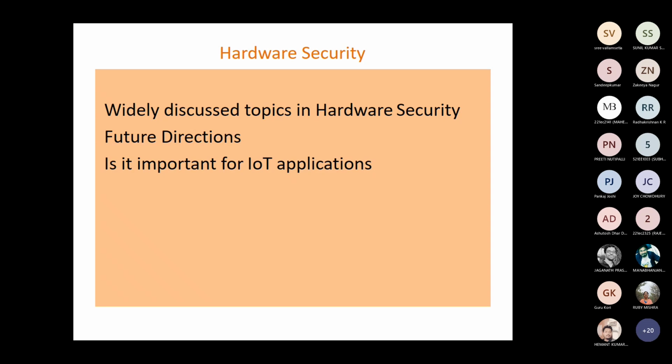Now, when I say hardware security, this will be a specifically designed integrated circuit that will have security right there, optimized for that. And many times the question comes whether you are going to use an altogether separate hardware for this. The answer is not necessarily. Sometimes it's the same IoT processor, but we add a piece of hardware into that processor, and that part is exclusively designed for security, which will take care of that.